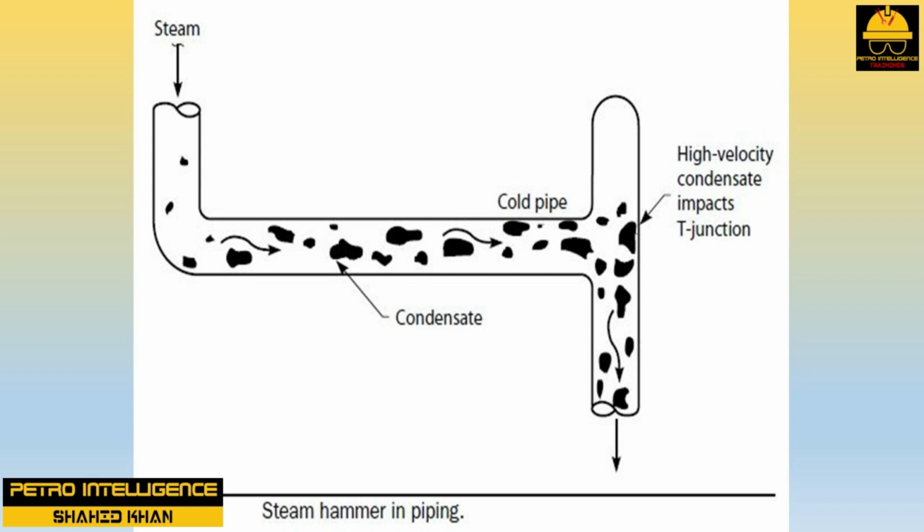Introducing condensate from high-pressure steam traps into the low-pressure condensate collection system will generate steam. For example, passing 1,000 pound/hour of condensate from a 160 psig reboiler into a 20 psig collection system will generate about 100 pound/hour of steam. More importantly, the volume of flow will increase from 20 cubic feet per hour to over 1,000 cubic feet per hour, as a result of flash vaporization.